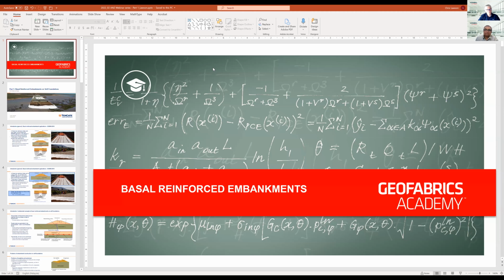except where the surface of the soft ground, if you're applying it directly to the surface of soft ground, is very soft. In that case, if it's very soft, you probably are going to need a separator beneath the geogrid to prevent any soft mud from coming up through the geogrid. But generally, if you've got a good vegetation crust on the surface, slightly over-consolidated surface, then if you're thinking of using a geogrid there, you probably don't need to use a separator as well as the geogrid.